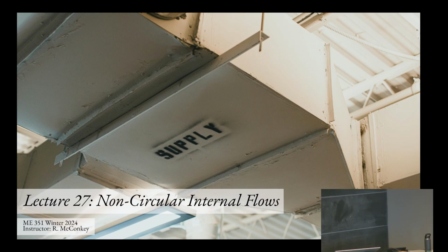What about in terms of why don't you think they build square pipelines? Why are pipelines round? Strength. Yeah, strength. So the circle is a really good shape to be able to take high pressure. If you try and put that pressure through a duct, you get concentrations in the corners, and the thing will rupture more easily. So for high pressure stuff, you use circles, and for more spatially efficient stuff, you can use rectangles or squares. Any other design advantages?